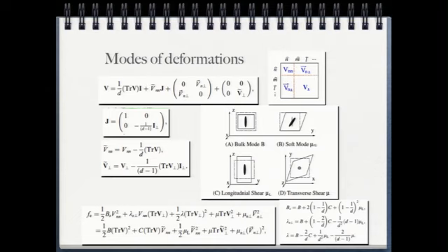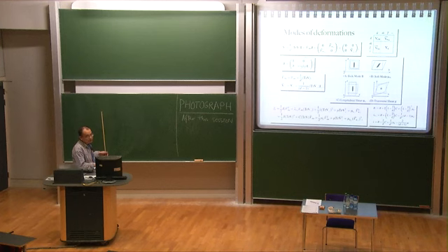Let's look at this mu_L. V tilde NN is the stretch along the director and the isotropic shrink in the perpendicular plane. So it's what we call a longitudinal shear. It preserves the volume, so its modulus is called mu_L. And we have this transverse shear, which is a shear deformation confined in the perpendicular plane. That's the V tilde perp, and the corresponding shear modulus is mu.